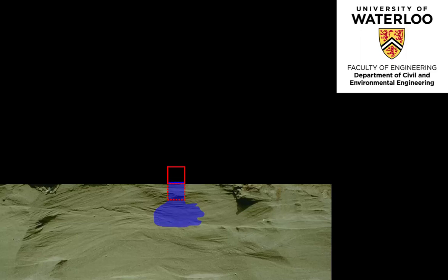However, central to the assumptions of employing this approach is that infiltration occurs in a vertically downward one-dimensional direction. However, arising from the three-dimensional geological environment, transverse dispersion of the moisture front occurs, which can result in an overestimation of the volume of water contributing to a spatially one-dimensional infiltration assumption.